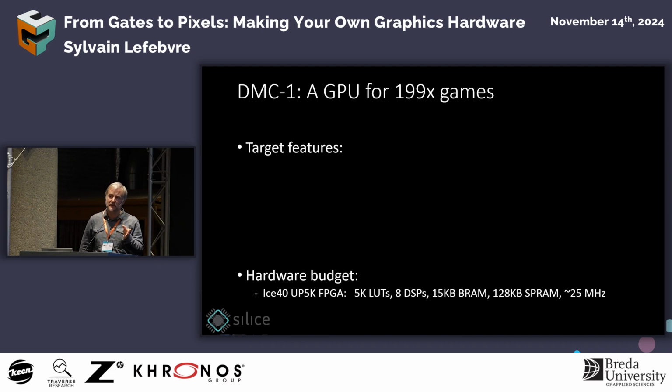It's an FPGA that is very popular in the hobbyist community, the reason being that it's a very nice sweet spot in terms of cost. It's only a few dollars, and the features it provides are 5,000 logic elements, but also 8 DSPs. The DSPs are hardware multipliers which are distributed inside the FPGA fabric, inside the grid of the FPGA. And the synthesis tool, Yosys, will know how to map multipliers to these hardware blocks so that you don't use your logic elements to implement multiplication, and you get very fast multiplications in these blocks.